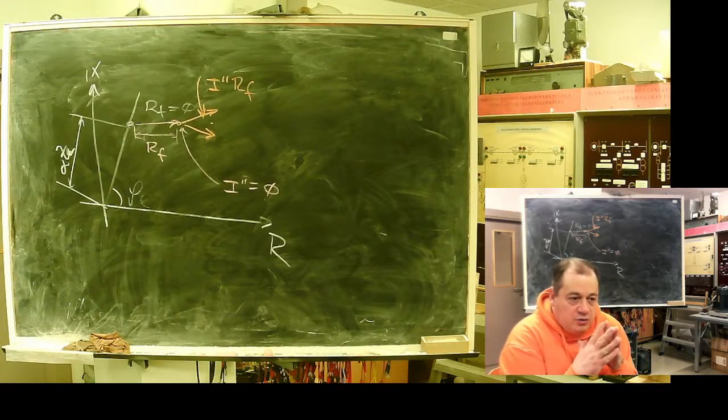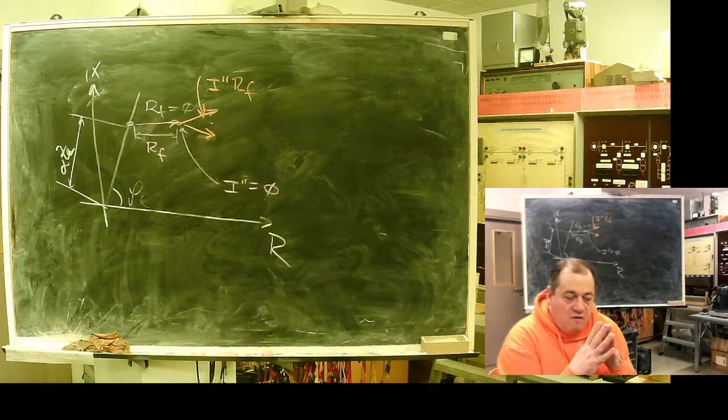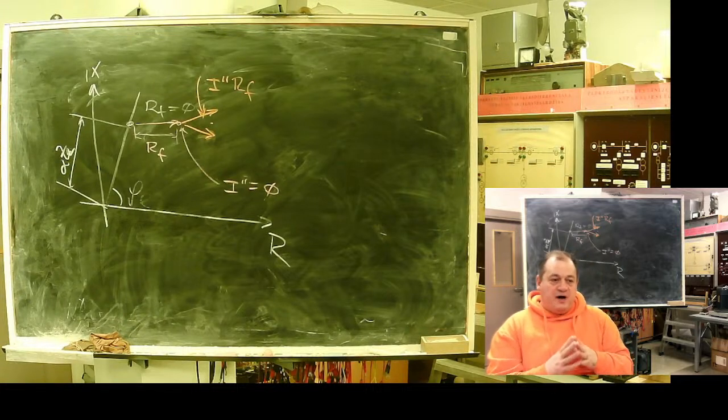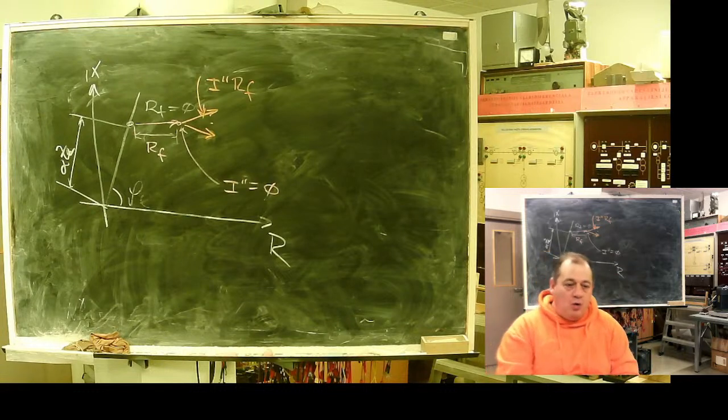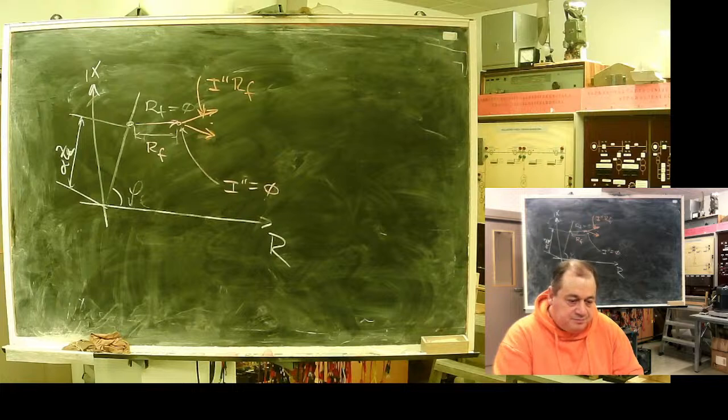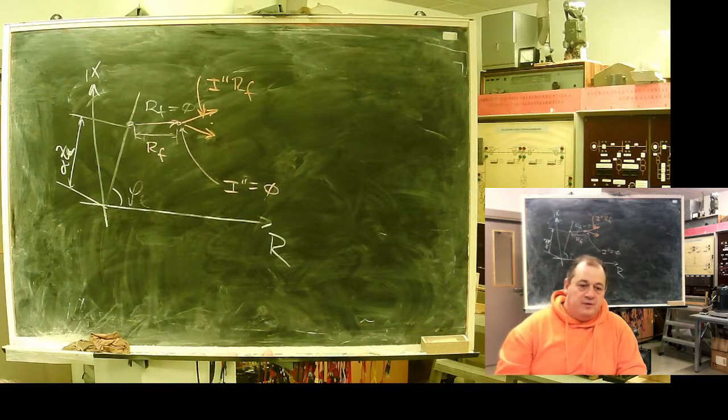If you are designing protection for areas where high transient resistance is expected, take care. Sometimes to prevent non-selective operation, a negative slope of the first zone may be required. It can be a problem, really.